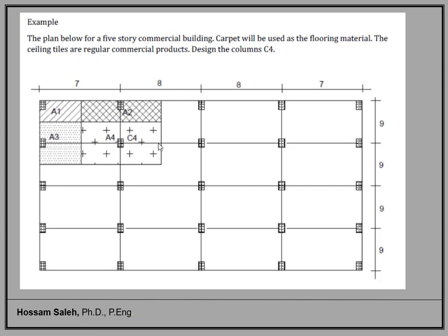Now our starting point is we want to calculate the load first, and then we can determine the cross section of the column and the reinforcing bars to make sure that this column can resist this load. And we want to make sure that it will be an economical design, so it's not over-designed, and it should be safe. So we have a balance. We also have to look at the economical side of the design and the environmental impact. We don't want to use too much material, and we want to use enough material for the project. So let's start to design this column.